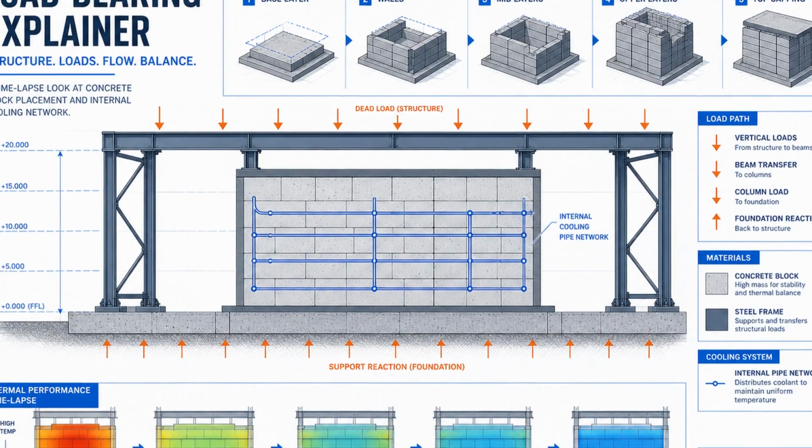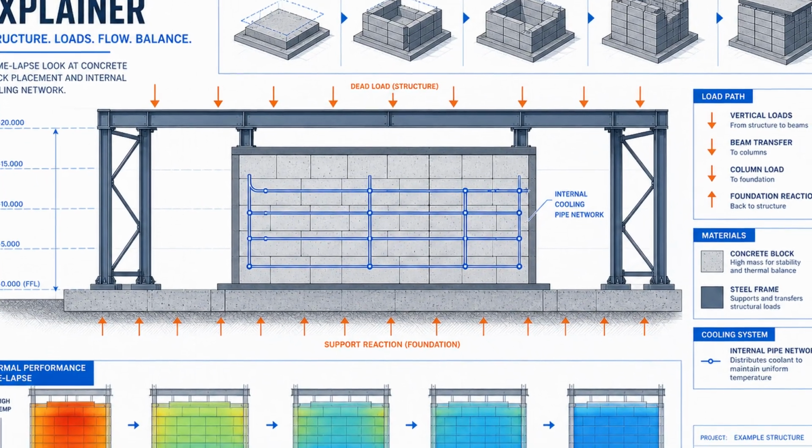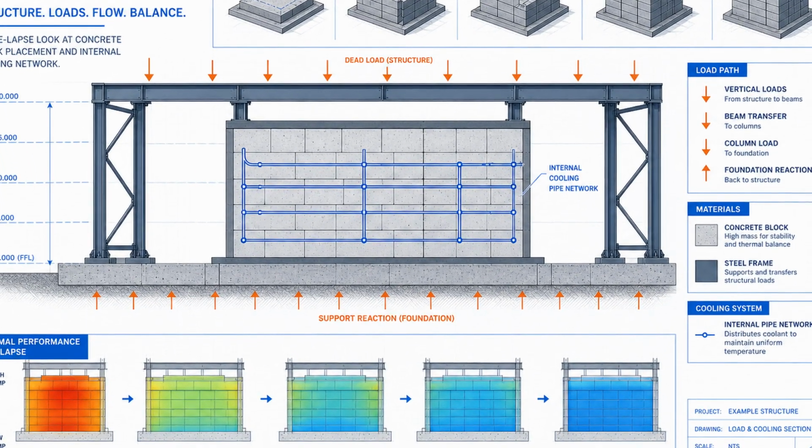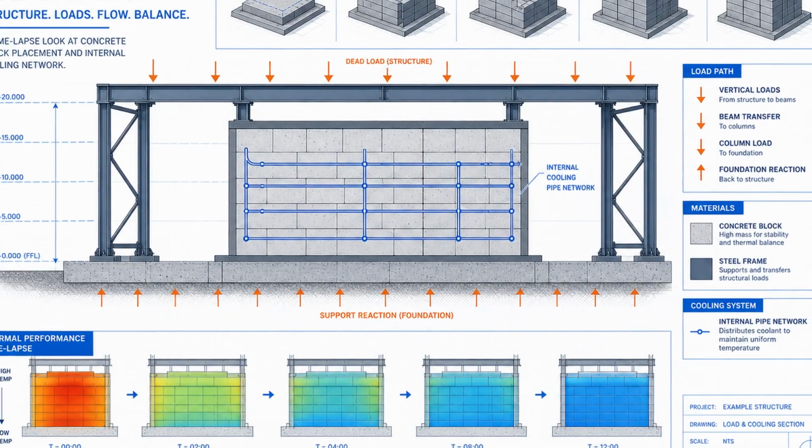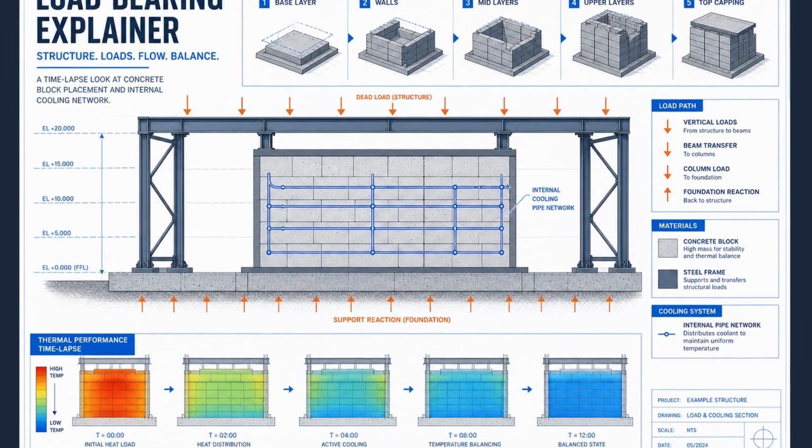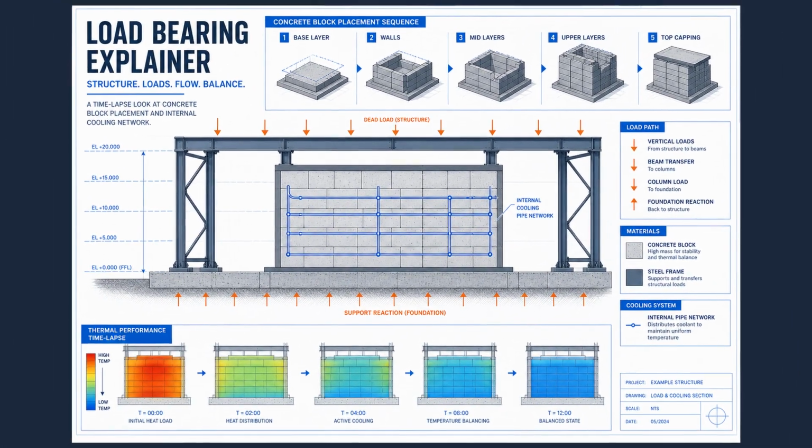Mass concrete generates heat while curing, then cools and shrinks. Without planning, that can cause cracking. Engineers place concrete in lifts, use cooling pipes, and control mix design to manage thermal gradients and long-term strain.